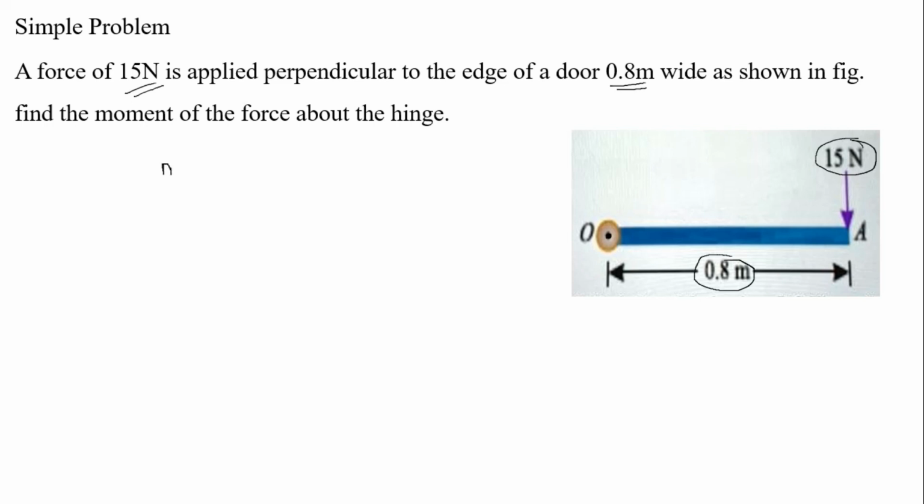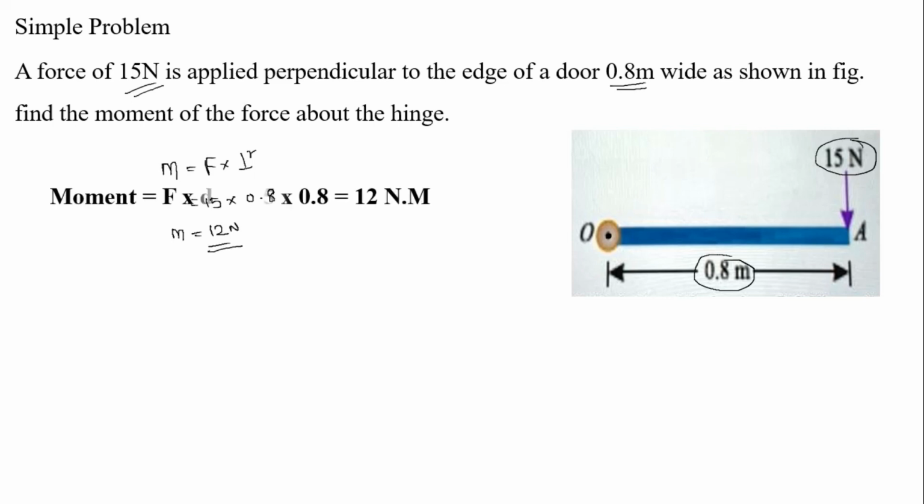So moment is equal to force into perpendicular distance, which is 15 into 0.8, which is equal to 12 Newton meter, right? Because the unit of force is Newton and the perpendicular distance is in meters, the unit is Newton meter.